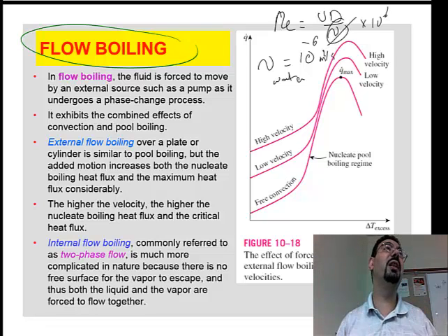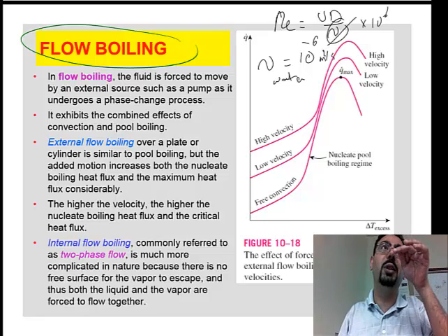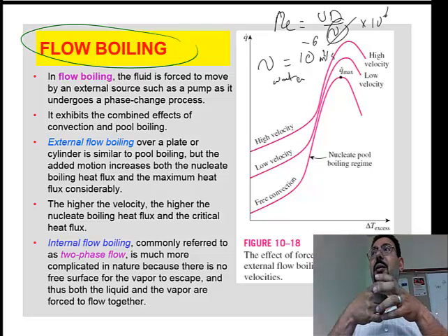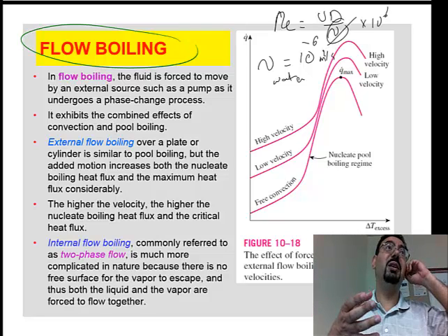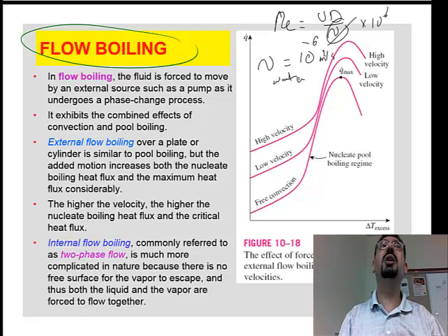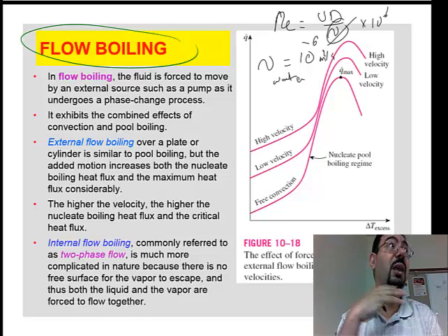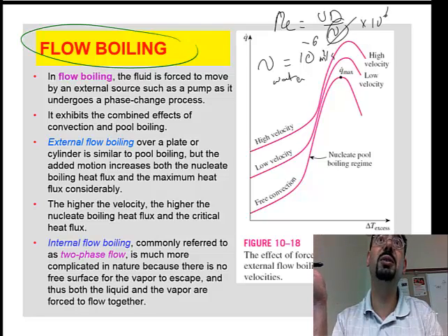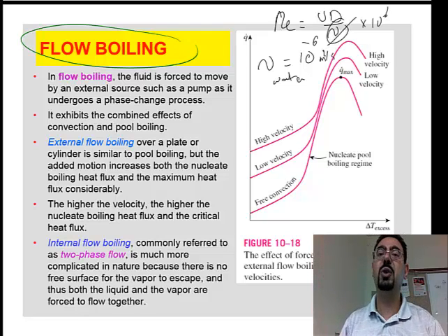So anytime the water is moving in a decent pipe, not 0.1 inch pipe, but a decent pipe, 0.1 meter, 10 centimeter diameter, 0.1 meter multiplied by 10 to power 6, already 10 to power 5. And so the V can be anything, and the Reynolds number is already turbulent. So that turbulence makes huge mixing, and of course it improves the temperature distribution along the walls, right? And wouldn't really let any hot spot happen near the walls. So as a result, that's what you see.